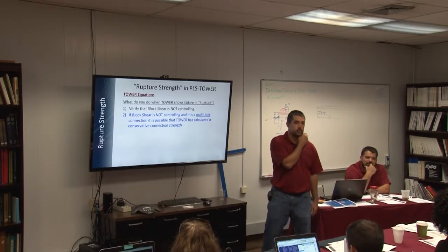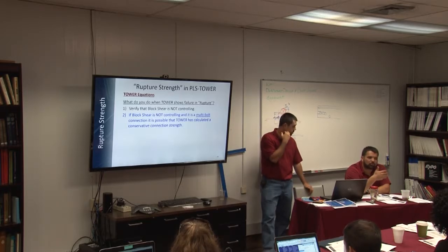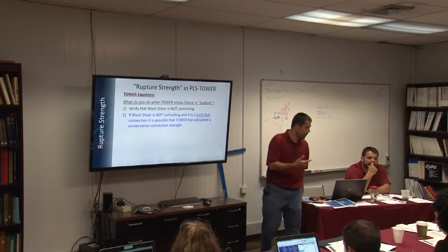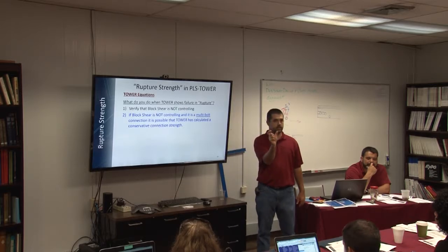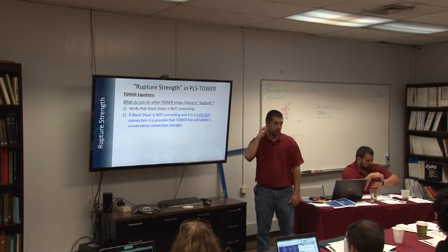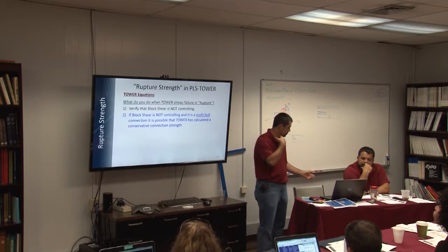Also, if the load goes up too, right? A couple of the parameters on rupture are load based. So if the load number goes up, reconductoring or whatever. That's actually a really great point. One of the minimum edge distances was based off of what the demand was per analysis. If I reconductor and my demand goes up, all of a sudden that rupture strength, that end distance, may not meet anymore because I based it off of the original design load and my loads went up. So that's a good point.